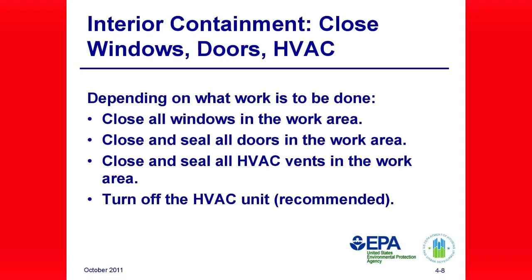Close and seal HVAC vents. Heating, ventilating, and air conditioning (HVAC) systems distribute air throughout the building and thus can also carry dust to other rooms. If possible, turn off the HVAC system for the work area. Close the HVAC supply and return vents in the work area and then cover them tightly with plastic sheathing to prevent air from blowing through the dust into the system or throughout your work area.